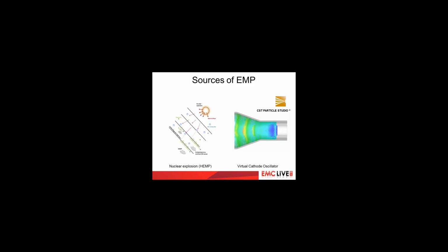High-altitude nuclear detonation produces an immediate flux of gamma rays. These photons in turn produce high-energy free electrons by Compton scattering. The scattered electrons are trapped by and spiral around the Earth's magnetic field, which gives rise to an oscillating electric current. And this current gives rise to a rapidly rising radiated electromagnetic field called a high-altitude electromagnetic pulse, or HEMP. Because the electrons are trapped essentially simultaneously, a very large electromagnetic pulse radiates coherently. And the pulse can easily span continent-sized areas. This radiation can affect systems on land, sea, and air.